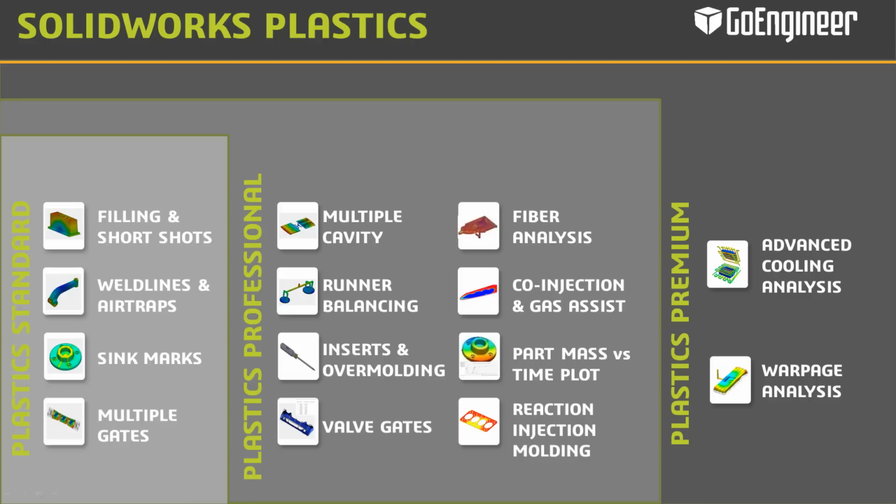This is the highest level package. So you get everything in Standard and Pro and Premium. They've included the advanced cooling analysis and warpage analysis. So these two go hand in hand. The cooling analysis will go through and analyze the variable cooling in your mold. An injection mold is never a completely uniform wall temperature. So being able to run the cooling analysis hand in hand with the warpage analysis is really great.